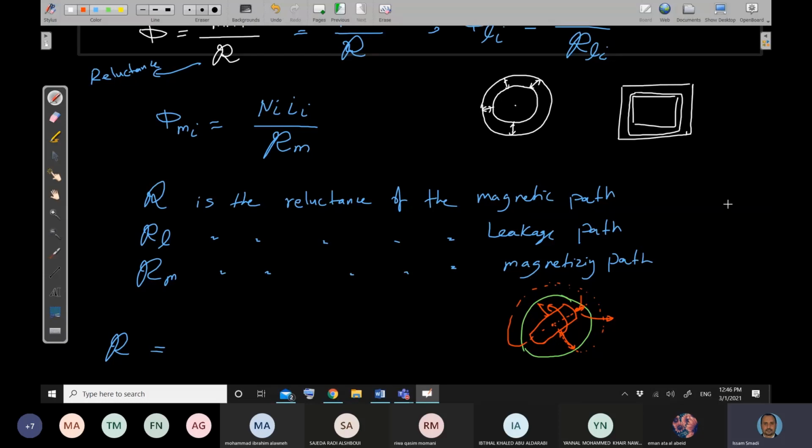The same thing here. If this one has the following shape, let's say. And let's assume here I'm having a coil. Now, this is a mover. And according to the magnetic field, the mover can move up or down according to the direction of the force. In this case, the magnetizing path is changing. Why? Because the gap is changing. But in the transformer here, the magnetizing path is constant, in the stationary magnetic circuit. Good.